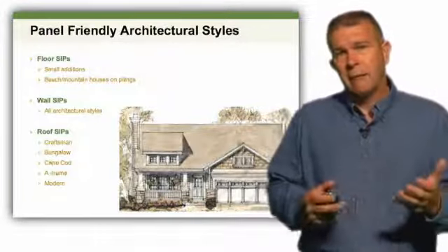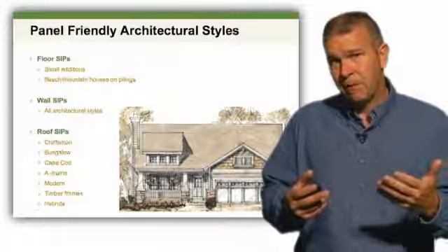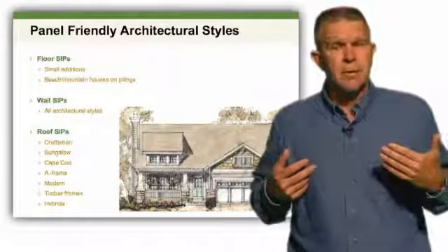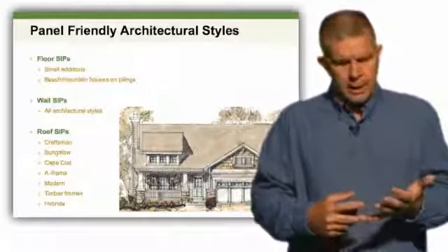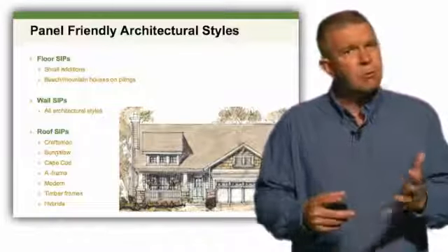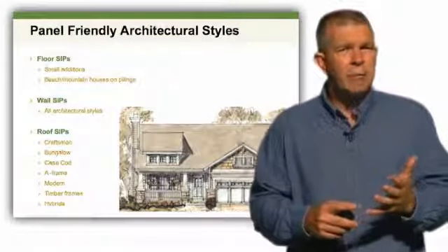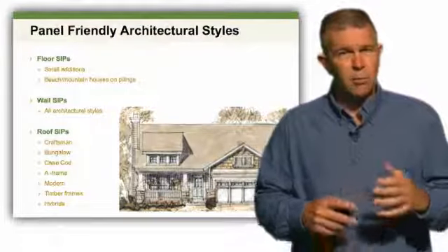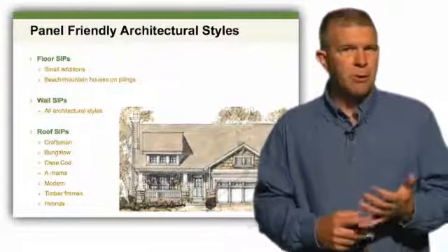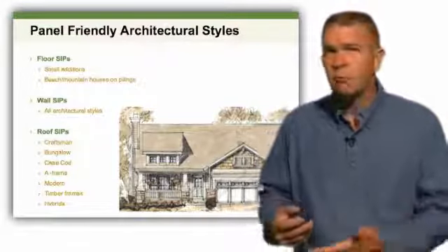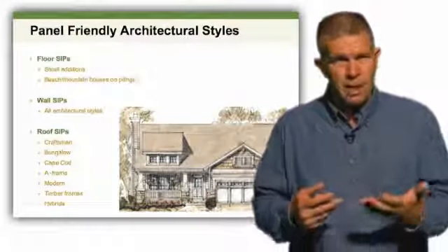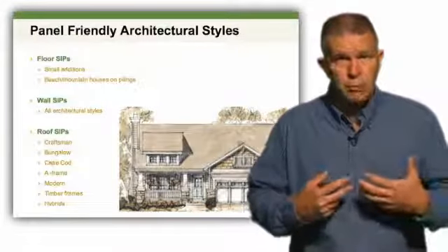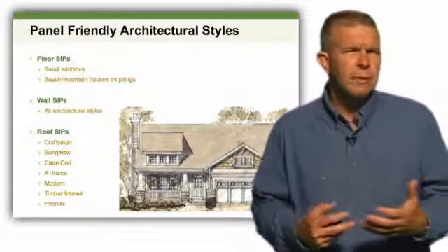You might look at the friendliness based on whether you're considering floor panels, wall panels, or roof panels. Let's start with the floor panels. As we've said before in the previous module, floor panels aren't commonly used, for a variety of reasons. But if we are going to use them, the areas where they might work really well is if we're doing small additions, or if we're building on top of pilings where we have Mother Nature blowing underneath of the structure and we want the insulating attributes of a SIP used towards our benefit, that's where it starts making good sense.